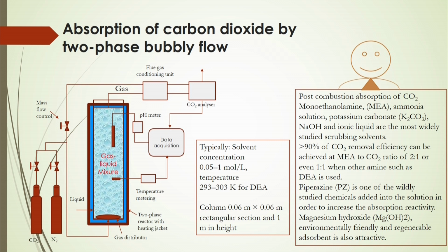There are several studies and research components here to increase the mass transfer efficiency. Sometimes if you produce finer bubbles of carbon dioxide, you get more surface area, and then you can have more mass transfer efficiency. So, more carbon dioxide gas within less time.